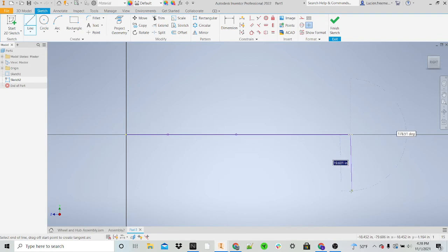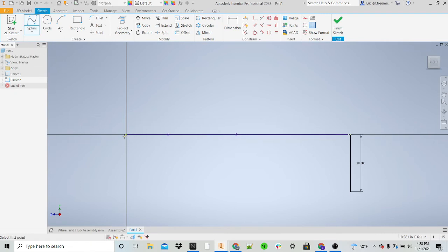Just go down from here. We'll just call our car about 20 inches down and go 90 degrees there. Now we can just create another spline that goes from the front of the car all the way down to the back, and that looks like a pretty nice shape there. So that's it, but again we have to delete this line.